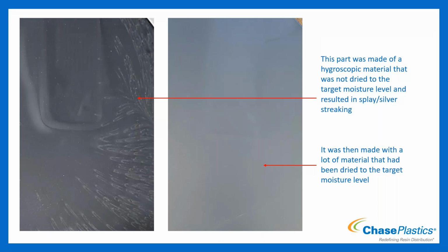You can kind of tell that the colors, and it could be that the part is expected to be, maybe you're mixing in orange and you expect the whole part to be that nice, maybe it's the high voltage orange, right? You expect it to be all across that nice orange color. Maybe it's a little bit lighter. Maybe you're seeing some swirling somewhere else because the color's not mixing in as well. Generally, visually, you can see the difference. I don't have a part or a picture with color swirled, but it will look a little different.